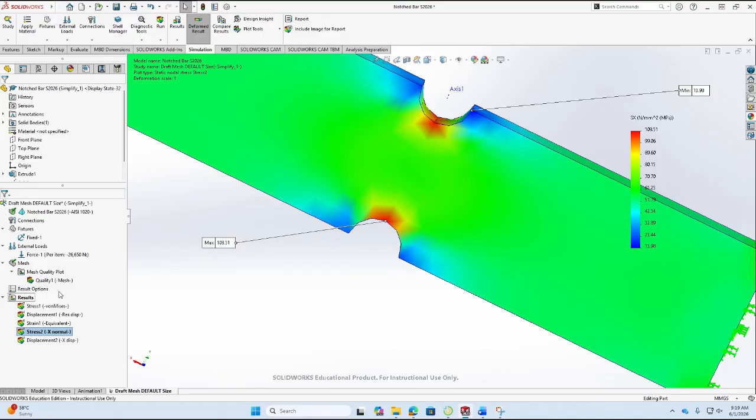And now rerun the analysis. Now, how do we rerun the analysis? Before we proceed, let us save this file by clicking on the save button, so that whatever analysis you have done so far, the results are saved. Instead of overwriting the results, because I want to compare them with this analysis, I will rerun the analysis by copying the simulation file. That will make it easy, because we just have to change the things that we want to change and not change everything in the model.